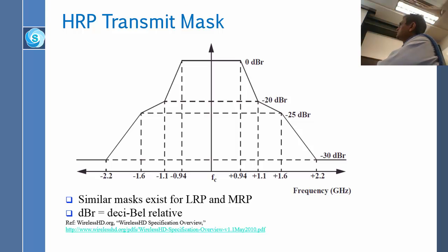You can see that even though the band given to you is only 1.76, which really is somewhere here, generally I would have expected that this would be 1.76 right in the center. But this is more than 1.76. So the rest of it is overflowing into the neighboring channel.